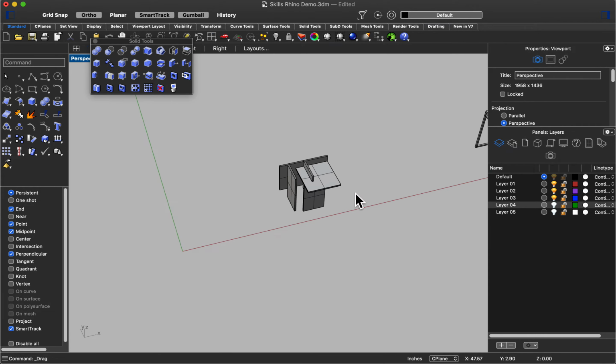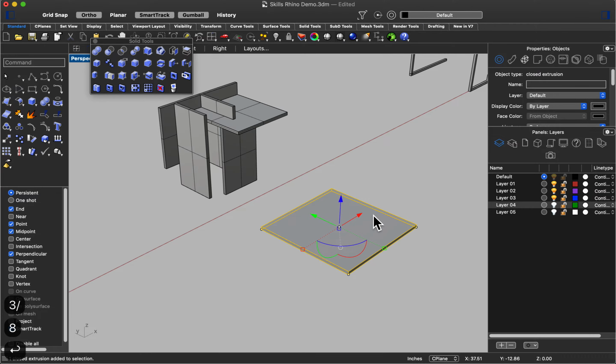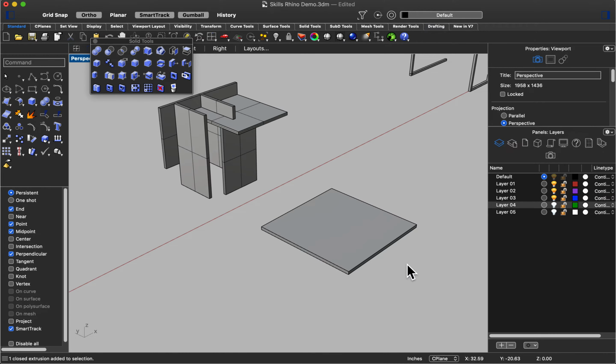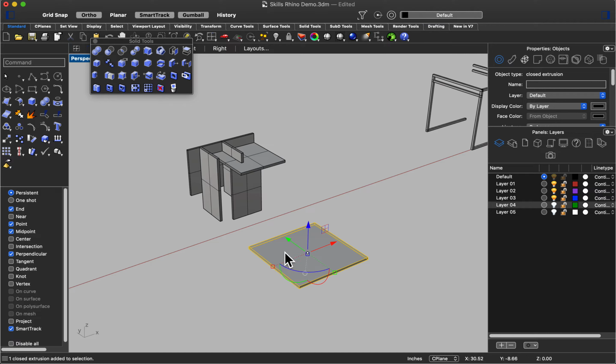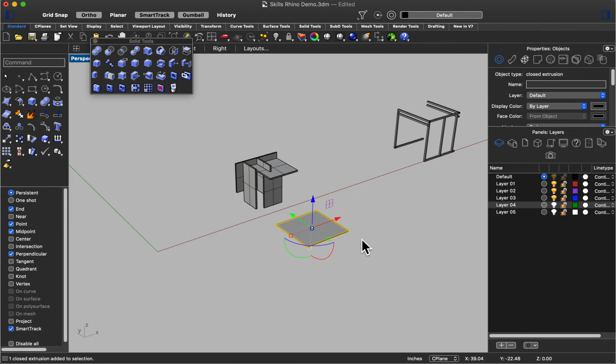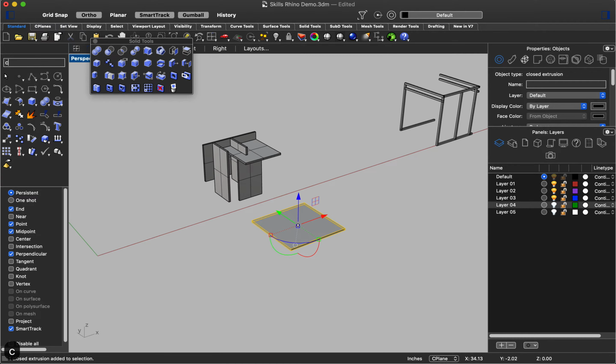But I'm going to give these planes some thickness. I couldn't really remember how thick they were, so I'm just going to extrude it by typing extrude curve. I'm going to extrude by 3/8 of an inch and hit enter, and again, making sure that solid is selected so that I don't have a tube. So now I have this plane, and basically I can copy this. Let's copy this plane, and let's say I actually want to rotate that plane.